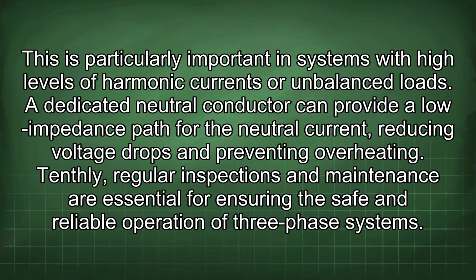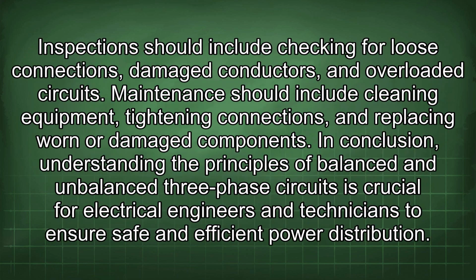Tenthly, regular inspections and maintenance are essential for ensuring the safe and reliable operation of three-phase systems. Inspections should include checking for loose connections, damaged conductors, and overloaded circuits.